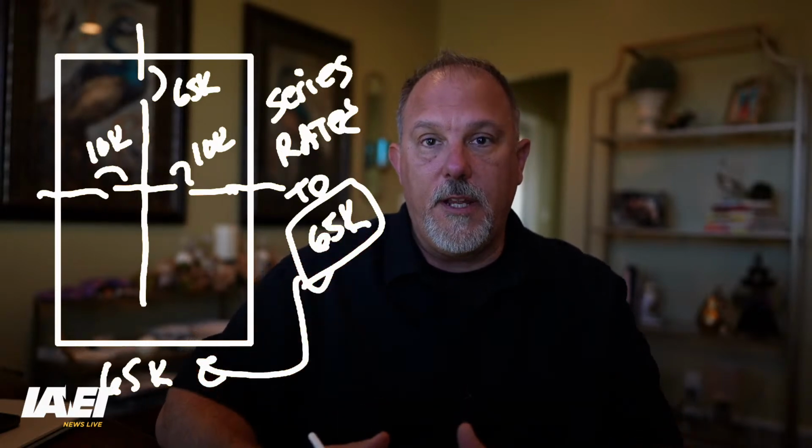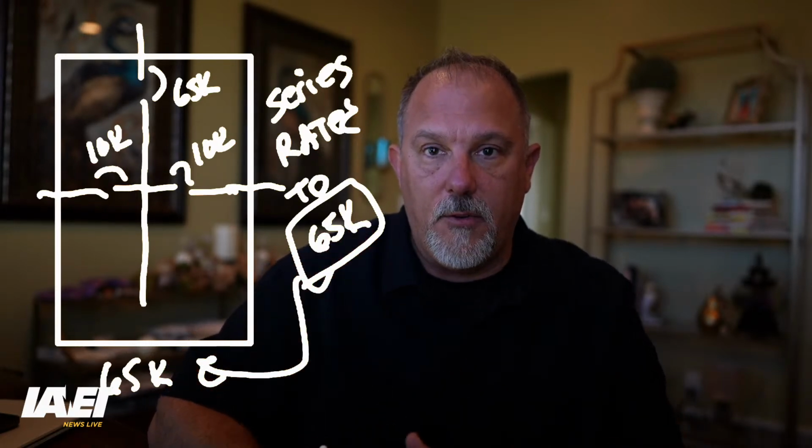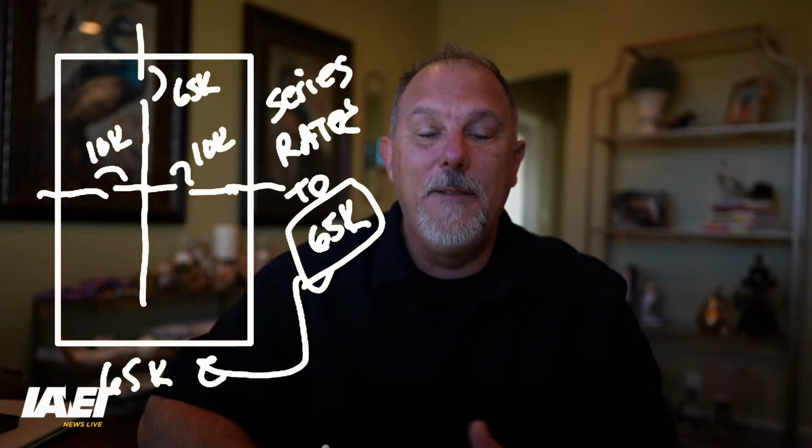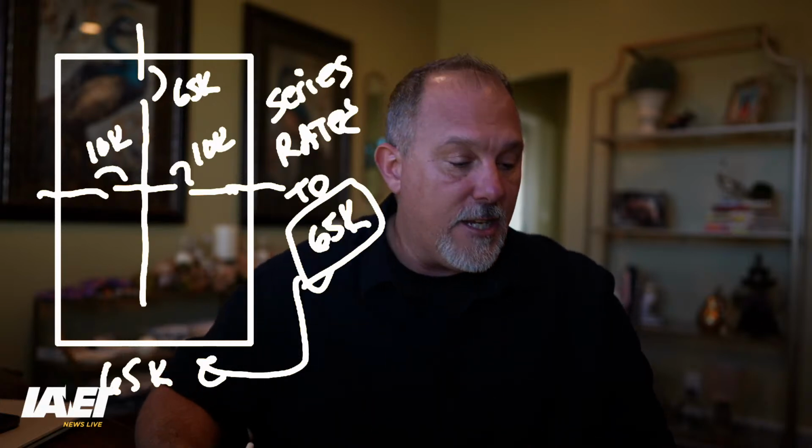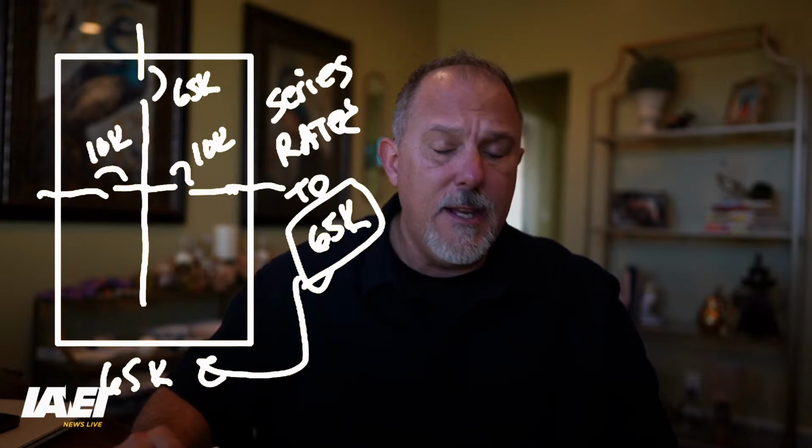Because the short circuit current rating of a panel board, which is not a UL 409, is based upon the components, but it's very similar to a UL 409 industrial control panel. The difference is that in an industrial control panel, you're going to have power distribution blocks, other types of overcurrent protective devices, conductors, maybe push buttons, lights, whatever, and the short circuit current rating is going to be the weakest link.